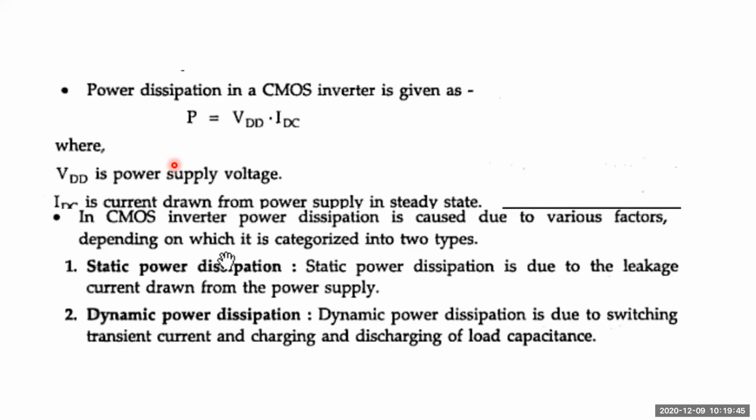The basic formula for the power dissipation will be P is equal to alpha times CV square F. So this is a basic formula, where alpha can be approximated to half, 0.5, depending upon the technology. It is alpha times CV square F, where C is the capacitive load, V is the voltage, and F is the frequency at which a signal is passing. That's a basic formula, and this is a general formula regarding the power dissipation. P is equal to V into I.